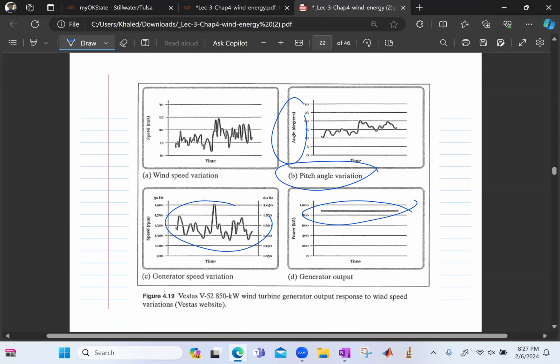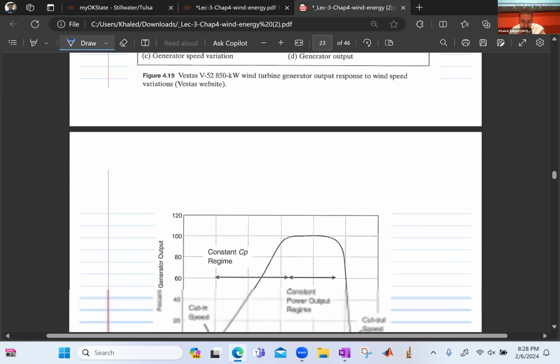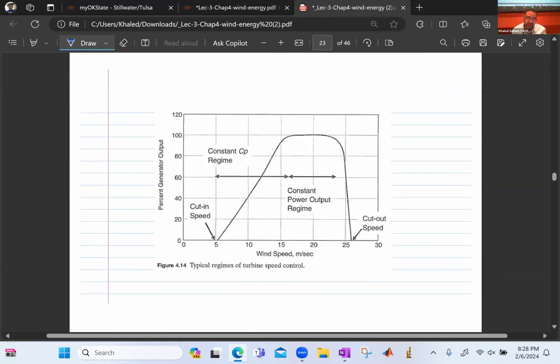So it plays with its CP so that you go up, you go down, I make myself do better, do worse so that I can guarantee my rated power. Of course, that is above V rated. If you are less than V rated, whatever, you cannot do anything. You will get less power. But above V rated, you can sustain that power. So you get that curve, right?